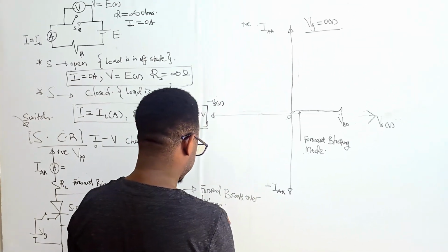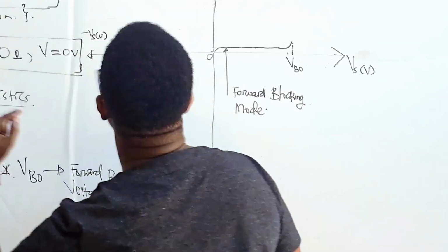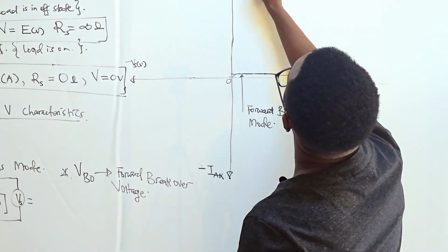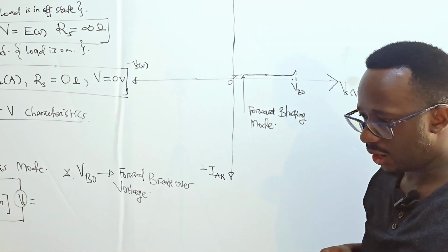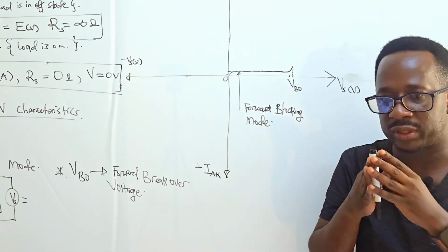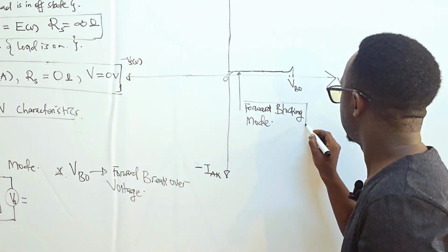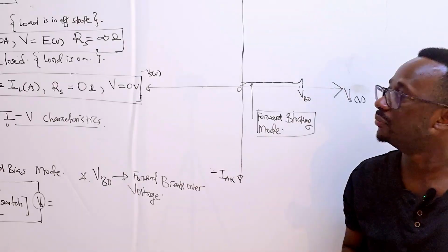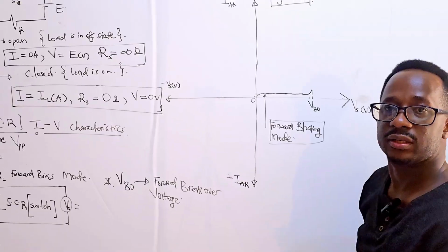This is a voltage beyond which, if we increase VPP further and further without applying any gate signal, it's like we are testing how far we can push the thyristor, to a point where it transitions from forward blocking mode to forward conduction mode, without the help of the gate signal.